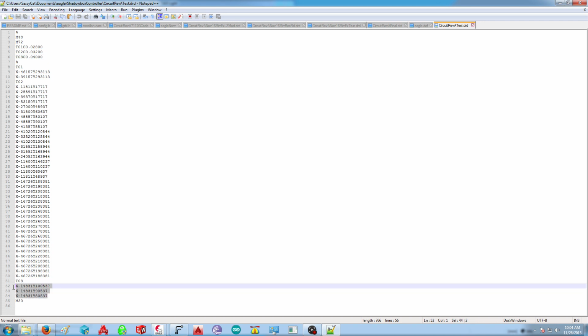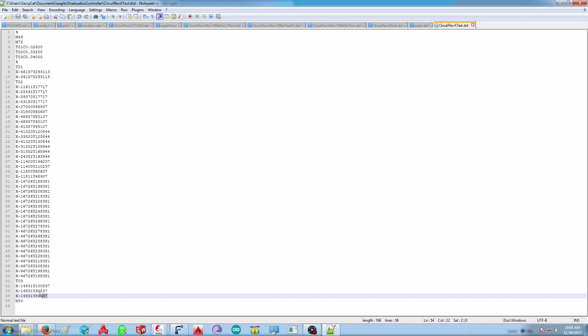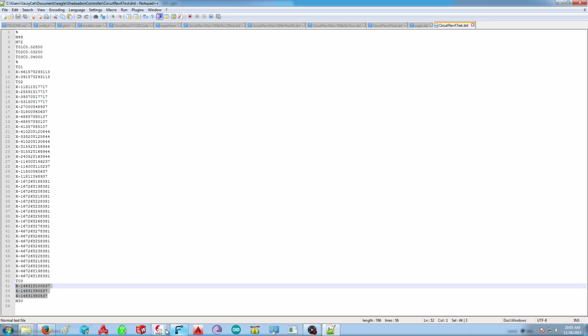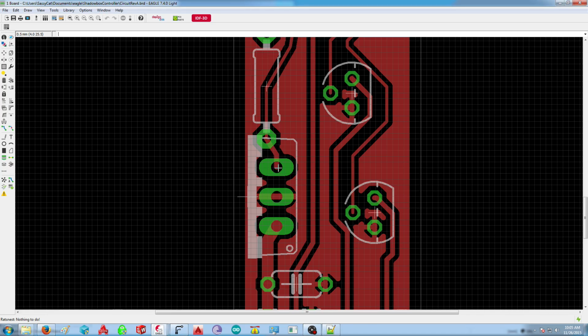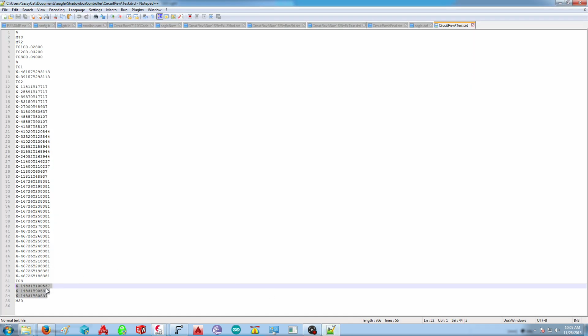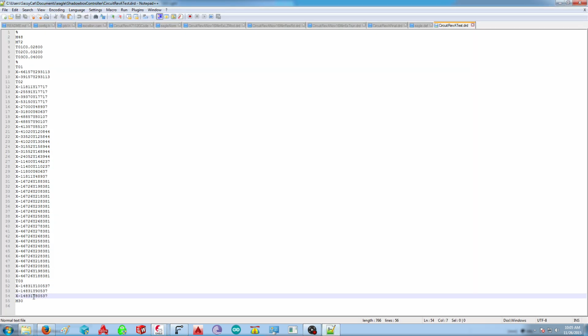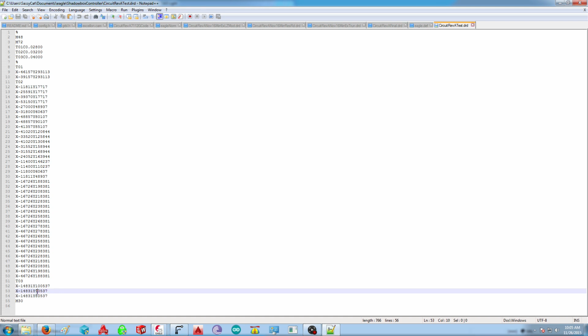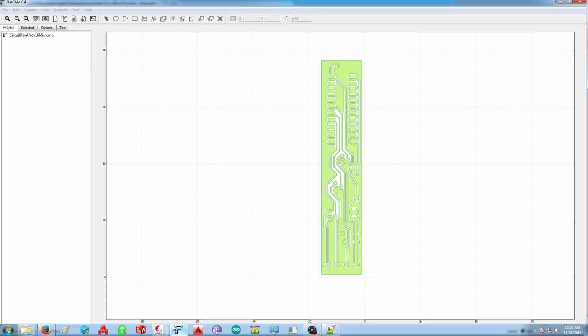And because there's only 3 points here, and it's the large hole, I figure that these 3 XY coordinates are for these three right here, especially because they have the same X coordinate. Like, yeah, it makes sense. Those are the 3 holes, right? And you can see that on the y-axis there's 8, 9, 10. But FlatCAM isn't going to interpret it like that.